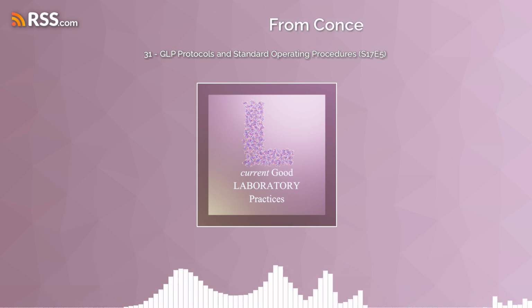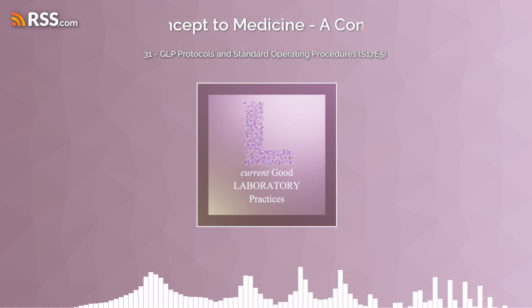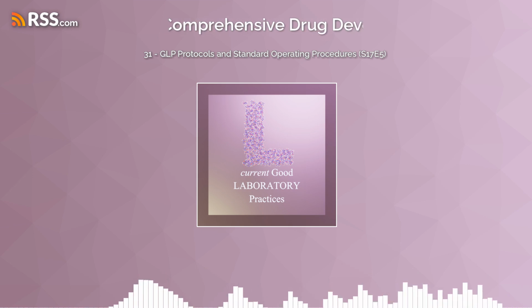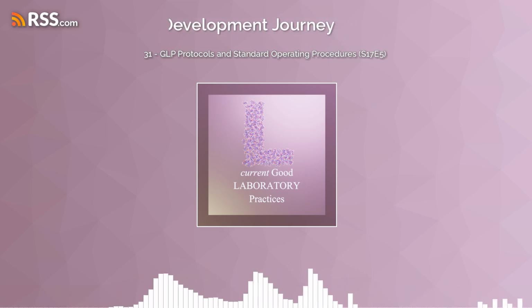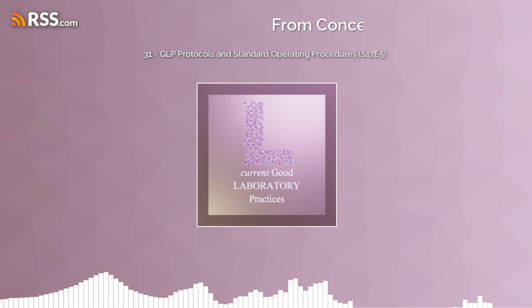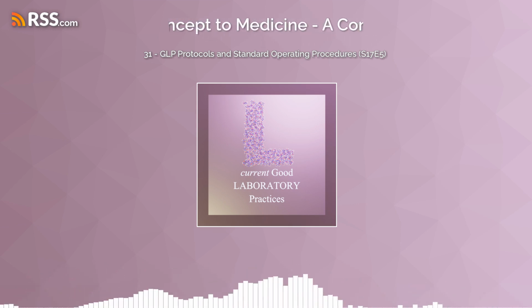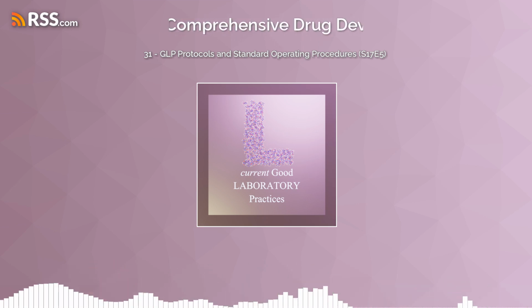Then there's fault tree analysis, or FTA. It's more of a reactive tool used when something has already gone wrong. It's a structured way to investigate how a specific failure happened, especially if there are multiple factors that contributed to it. It helps you trace things back to the root cause. So FMEA is like preventative maintenance, trying to stop those problems before they occur, and FTA is more like a post-mortem when something's already broken down. Got it. So is there a final piece to this puzzle, something that ensures these protocols stay effective over time?